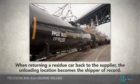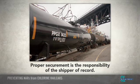It is important to remember that when returning a residue tank car to the supplier, the unloading location that prepares the rail car for return shipment becomes the shipper of record. It is the shipper of record's responsibility to ensure that the tank car is properly secured. If there is a leak during the return movement, the shipper of record will be held responsible for the incident.